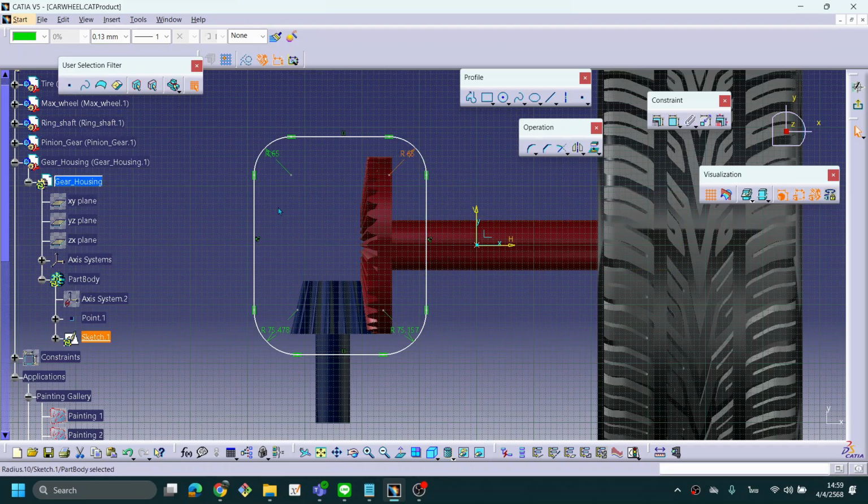Or you let the rectangular block go outside and use the edge fillet feature to create a smooth curve, a smooth fillet. You can use that way as well. And now I will show you how to clean up the sharp corner with the corner operation.